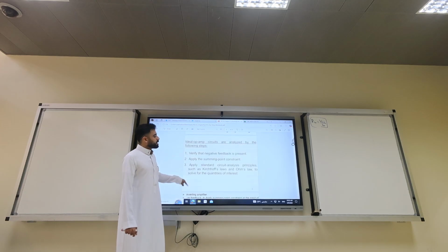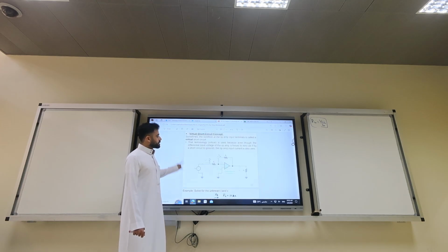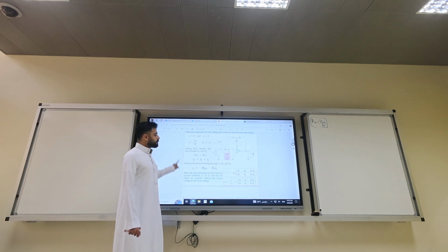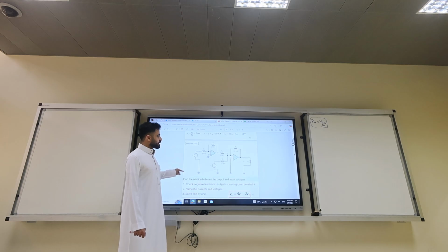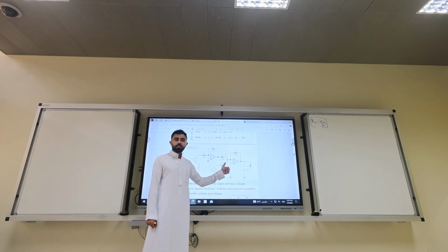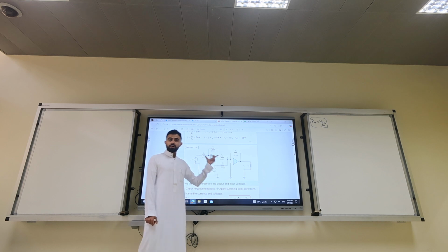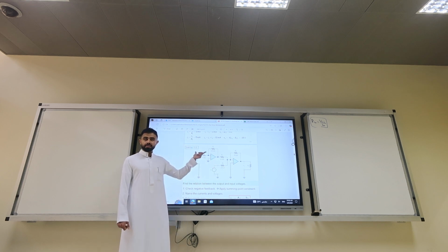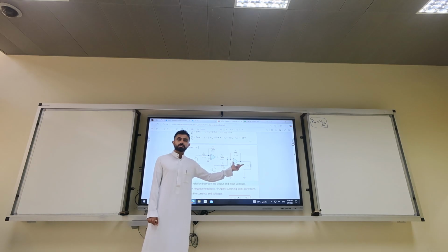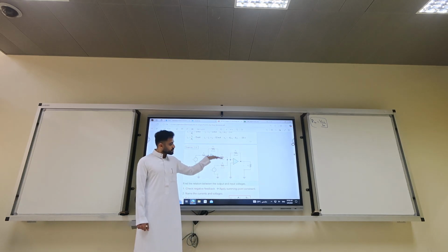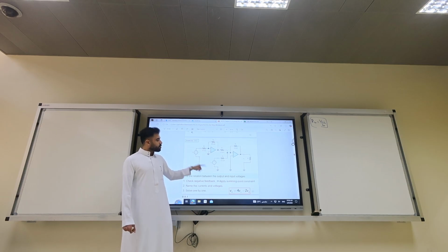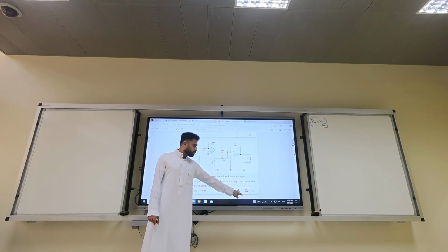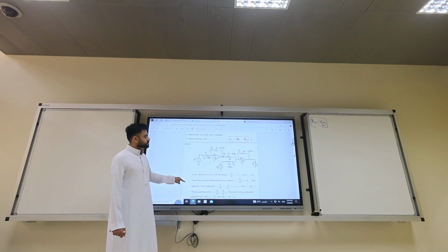But before we begin, let's do a quick simple example, or we continue the previous example that we did last time. Now, do you remember this two-stage example? We had here an inverting amplifier. Then we had a summer. It sums two inputs. So without doing complicated circuits, you can know that the output is 4 V1 minus 2 V2. And we did a numerical example here.